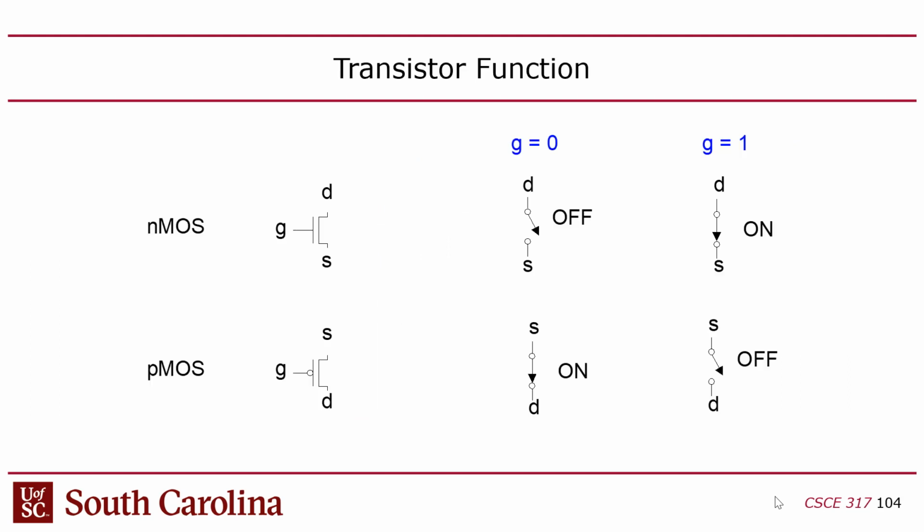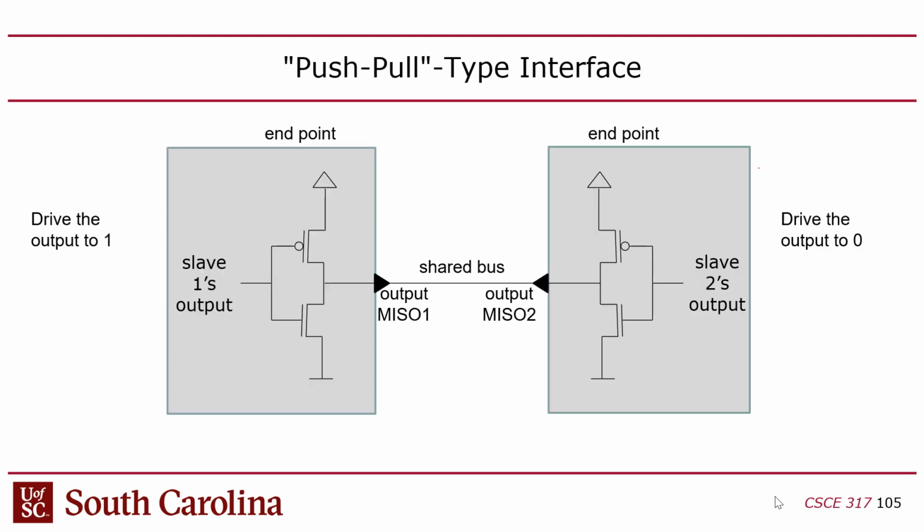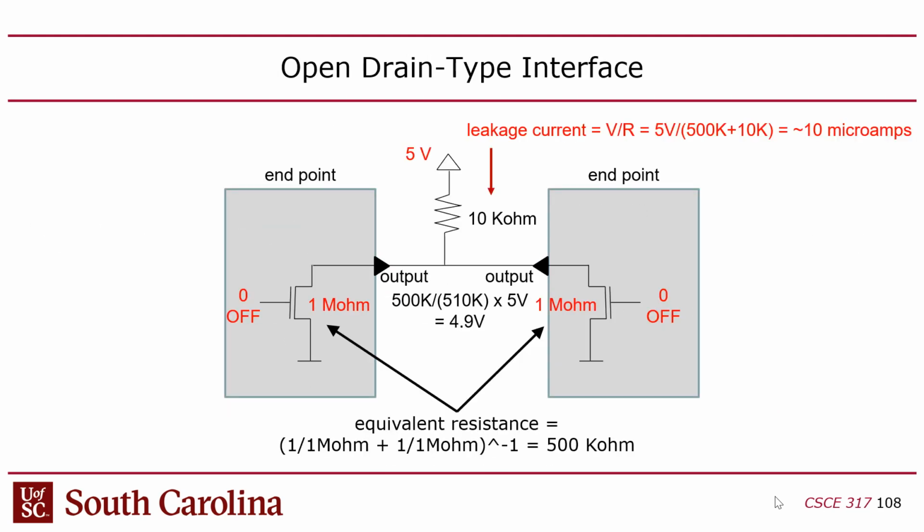the transistors have a source and drain, right? In the NMOS, the drain is the top terminal. On the NMOS, the source is the bottom. The drain's the top. And so if you notice that we're using NMOS here, okay, the drain's the top terminal, so this drain is open. Why is it open? It's not really open, it's connected to a resistor. Well, it's open because it's open to the world, connects to the pin that goes outside the chip, right? I guess that's why they call it open. That's what they mean, open drain, right?